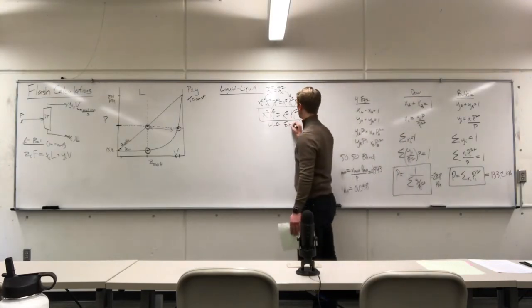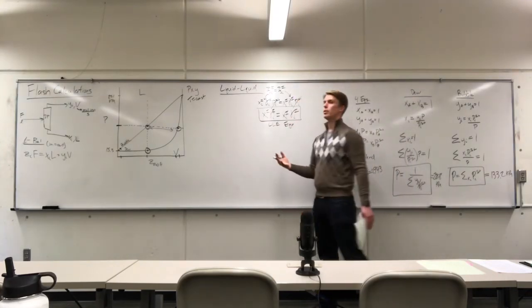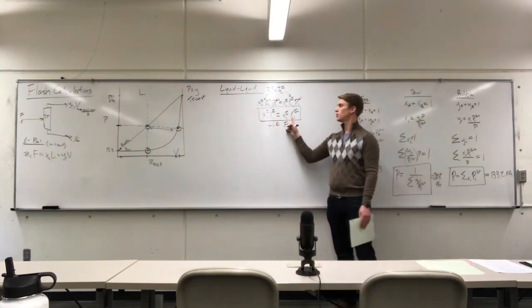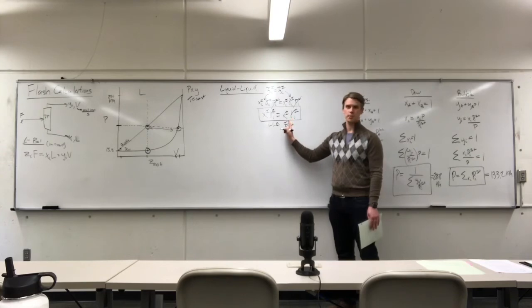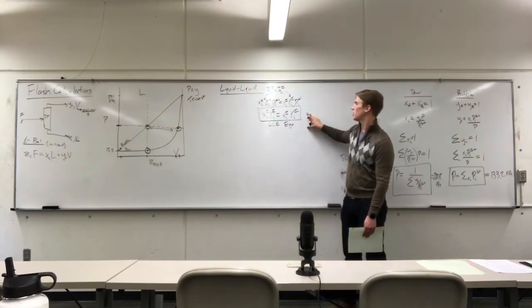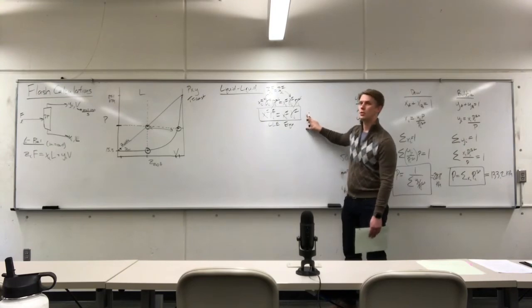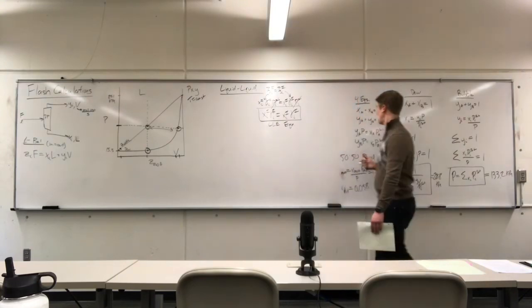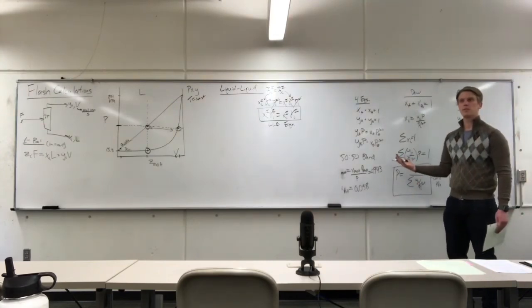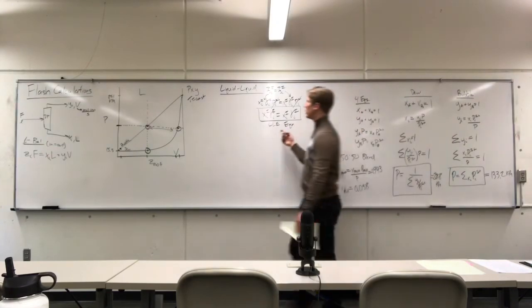Now, liquid-liquid equilibrium is kind of its own beast, because activity coefficients are typically exponential functions of composition. And so for a two-component liquid-liquid system, you have to solve basically two nonlinear expressions simultaneously, whereas for the vapor-liquid equilibrium system, assuming ideal behavior, it was relatively trivial. We did it in class. So in a liquid-liquid system,